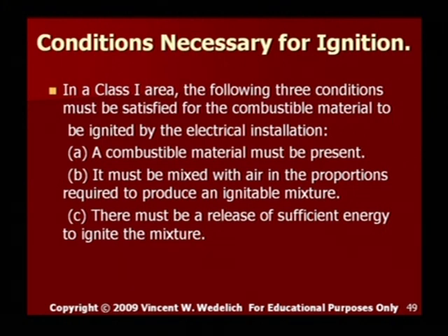We'll talk about this later, but there are things such as IS barriers, and these IS barriers actually limit the energy sufficient to ignite the mixture. If you have a source that is 2 watts or less, that will not ignite hydrogen.